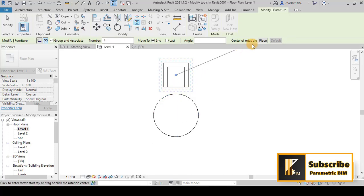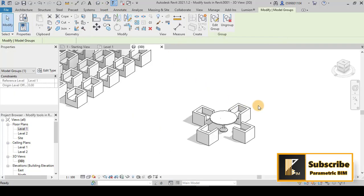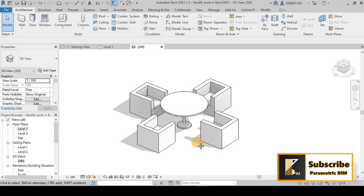I want to change it and place it at the center of the table. Then I will change the number to 4, and then click from here. You can also specify the angle, but I know that the angle is 90 degrees. So by one click I have 4 seats around this table.